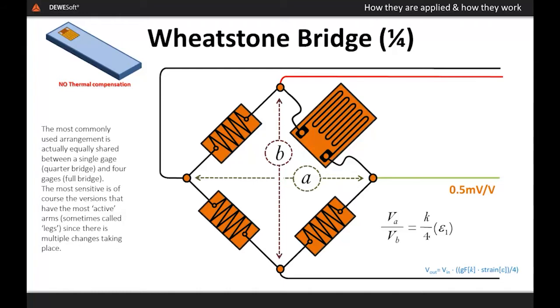A strain gauge doesn't just look like a small electric heater, it is a small electric heater. Where there is a current, there is heat. The current is very small, but there is still heat. In some materials, the surface can be affected by the heat, and on plastics, it can literally mean that your gauge is now on top of a small lake. Ironically, this is something we have seen too many times.